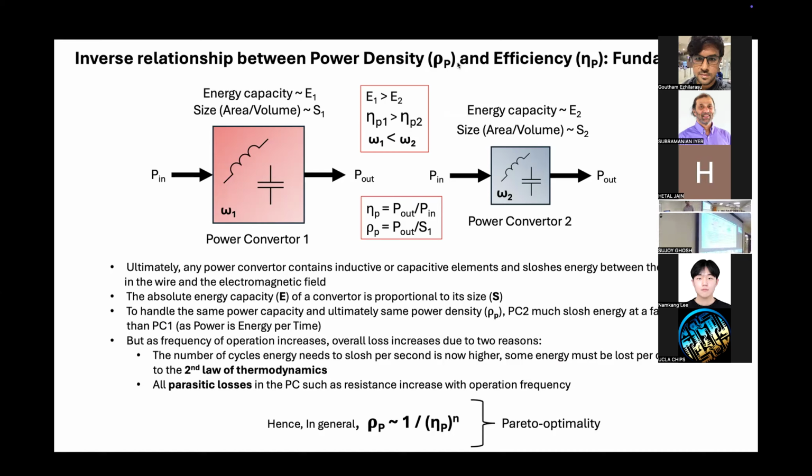Here you see a typical transformer structure we consider, with a bunch of magnetic materials with laminations, and this is the equivalent circuit of the transformer. Basically you have the resistance and inductance of the primary coil, and then you have this resistance that's used to model the losses in the magnetic core.